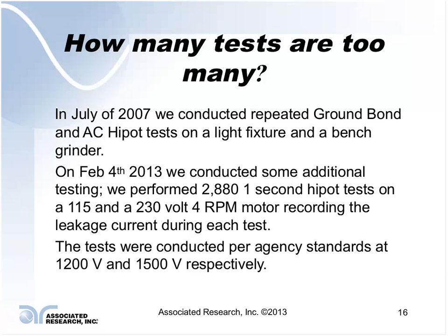And we did 2,880 Hipot tests on these motors, 1 second duration. The tests were basically conducted based upon the agency standards. The customer had recommended that the 115-volt motor be tested at 1200 volts, and the 230-volt motor was typically tested at 1500. So we went through and duplicated this.